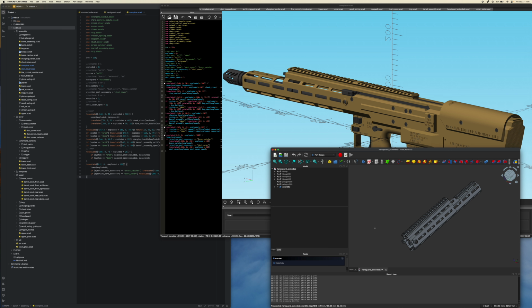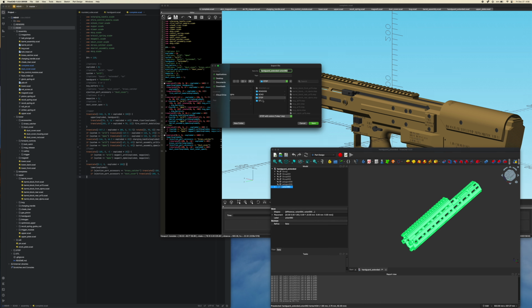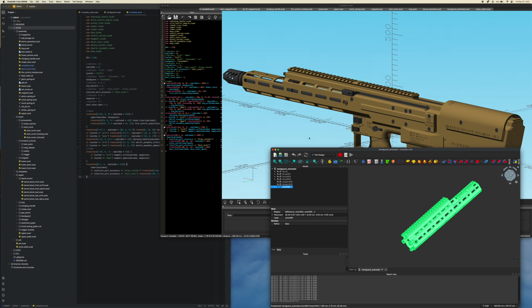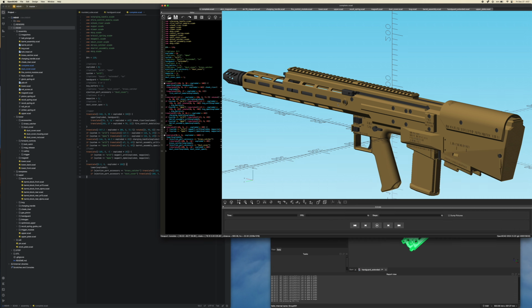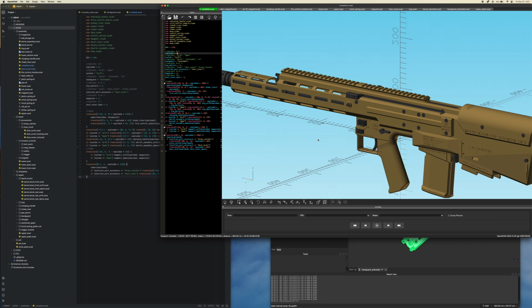So, you just want to click the top level geometry, which is just this union here in this case. And then once you select it, you just hit export, and then I just dump it in my step file folder. So then, yeah, just change the name, and then click save, and that's really it. I made another tutorial on this earlier. I think it's the first video on my channel. So I'm not going to go too much further into this.